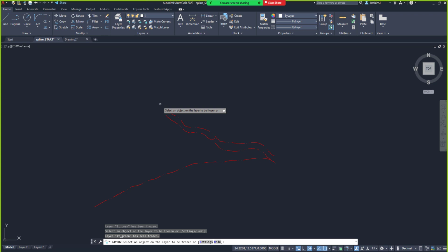But when you freeze that kind of layer, that is why most of the time we create all our design first, and at the end of our design, that is when we start adding our arch pattern on the regions or areas we want to put them. Are you with me? So basically, when you freeze a layer, it goes off your RAM and your graphics card, so your system gets to run even smoothly, right? Do you understand the contrast between the two?